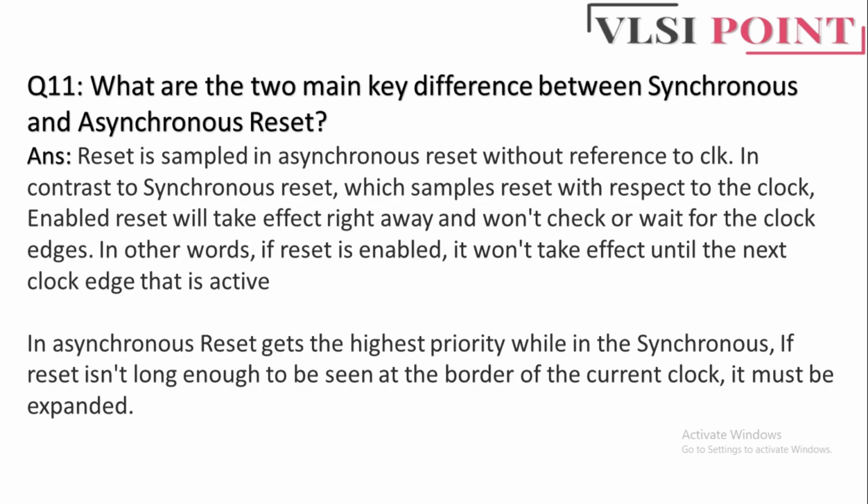Another difference is based on the design complexity. Synchronous reset requires the use of a flip-flop or other memory element to synchronize the reset signal with the clock signal. This adds some complexity to the circuit design, but it also helps ensure that the reset signal is properly timed and that glitches are avoided. However, in case of asynchronous reset, it does not require the use of a flip-flop or other memory element to synchronize the reset signal with the clock signal.